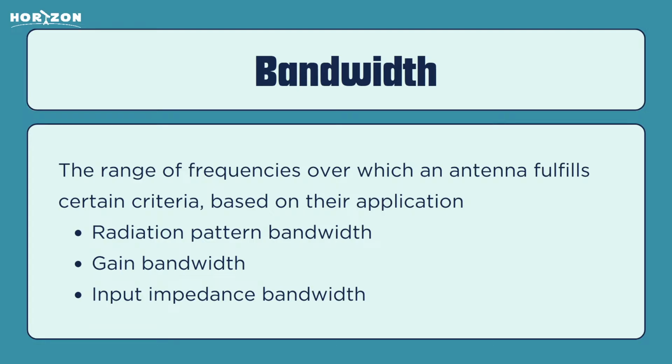They also have a gain bandwidth, which is the set of frequencies over which the gain exceeds a certain threshold. They also have an input impedance bandwidth, which refers to the frequencies where the standing wave ratio is less than a particular level, usually minus 10 dB.